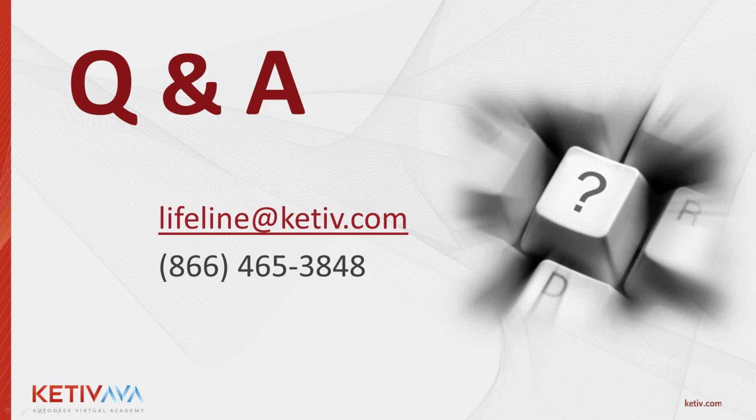Another one just came in. How does iLogic work with copy design? There's a couple of different ways. First of all, if you truly want to copy design, all of the rules are kept within the part itself and within the assemblies. So your rules are going to go over from one part to another as you do a copy design.